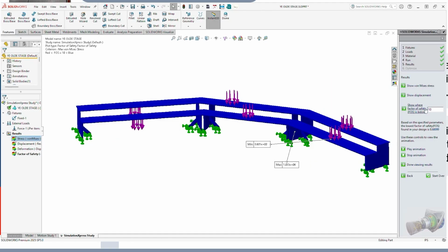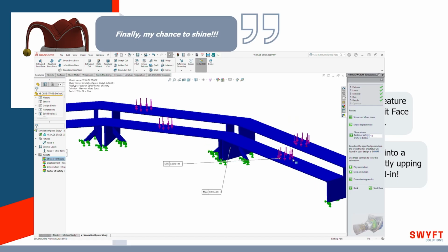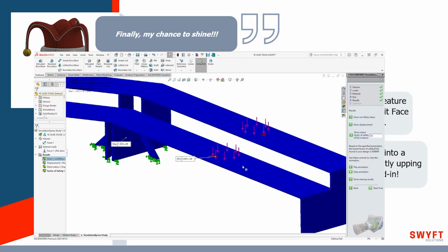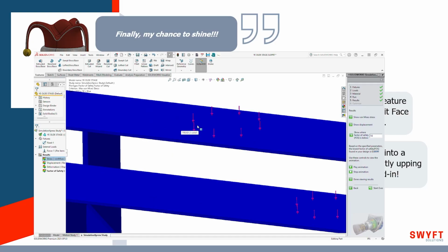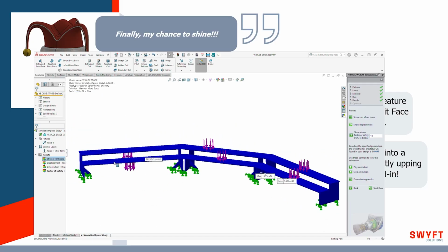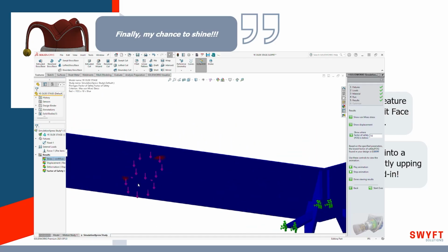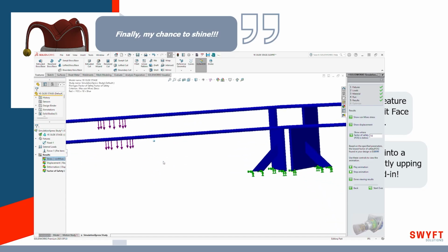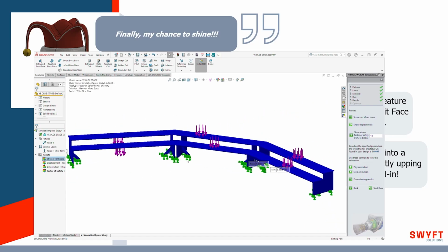But it's close enough to give us an idea of what's going to happen. And now I'm looking at the factor of safety. The factor of safety plot that I used before was 10. Using it in an assembly, we'll see some hot spots showing up, but it's not really telling us a whole lot. And that's 10 times 75 kilograms at each one of those, by the way. So that's enough force, well, that's more than if I had eaten a feast like we had out there today.